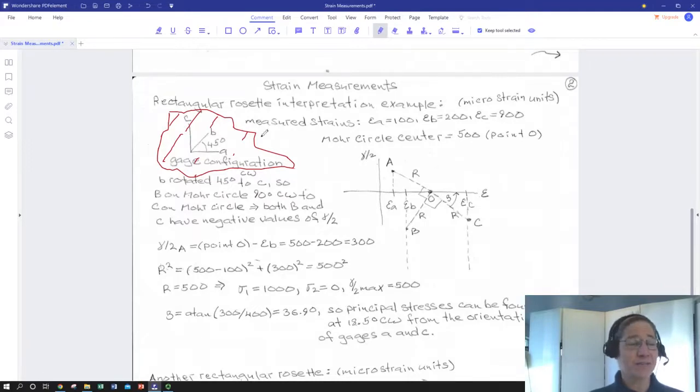We're definitely going to have plane stress considerations because there's no stress available on one surface, and we're not necessarily measuring strain in the direction normal to the surface. So effectively we can be confident with our plane strain assumption. We don't have to worry about another Mohr circle in a direction where we have to consider that Z normal coming out of the surface. So that's another nice feature of the strain gauge. It basically represents a plane strain consideration on your part.